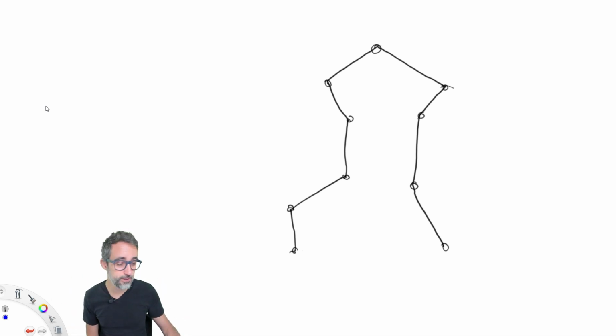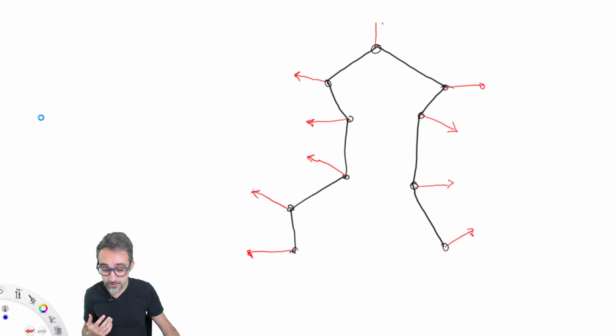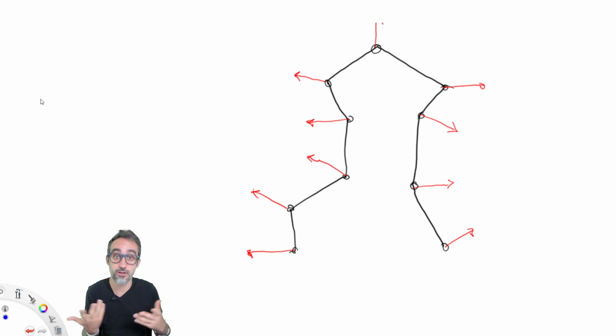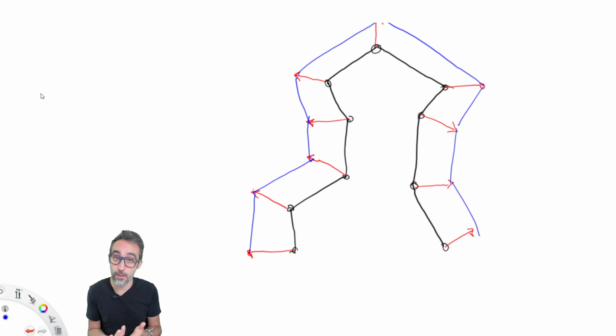So for example, if I know that a mesh has faces, that it has vertices, and that it has vertex normals, then very simple, straightforward modifications to this mesh could be, for example, taking each one of those vertices, moving it in a direction that is perpendicular to itself, so along the normal of the vertex, and then reconstructing a new mesh that has the same connectivity, the same faces, but the only thing is that the vertices are in a different location.